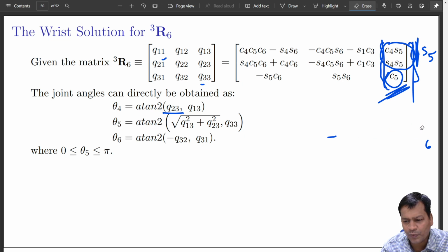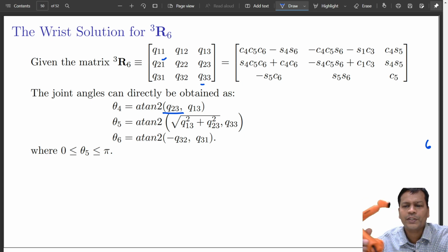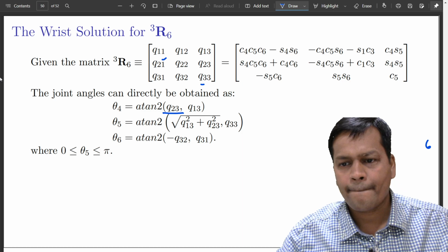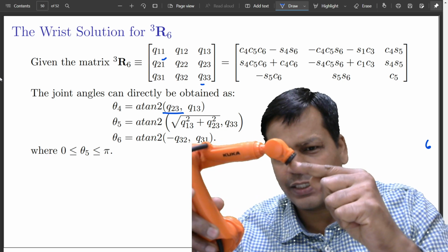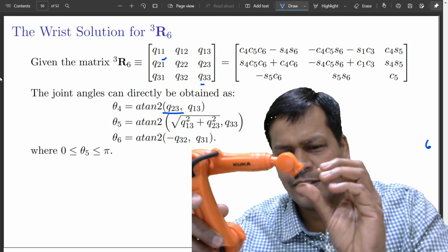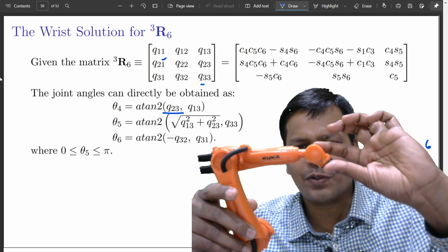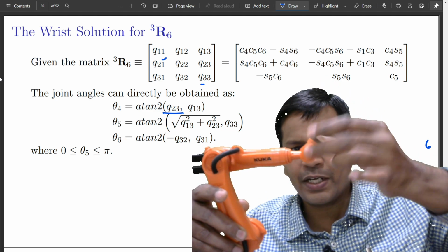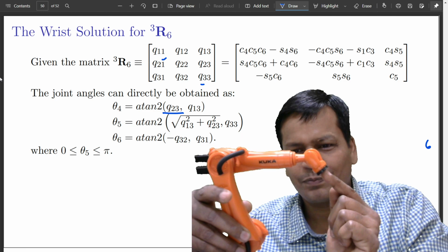For that reason, theta 5, I'll just show this video here. I'll zoom it out a bit. So this is your robot. If it is like this, it is pointing to this point. The same position I can reach alternatively by rotating theta 4 by 180 degrees. Then theta 5 went up, I went down and I reached the same place, no change, is it not?